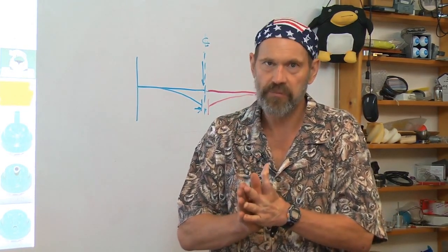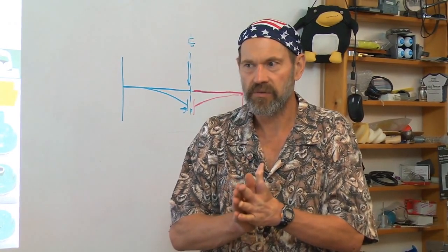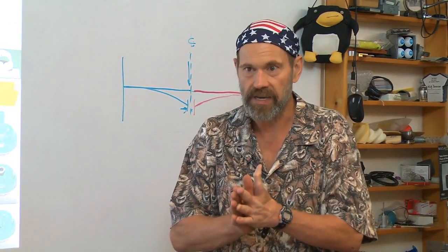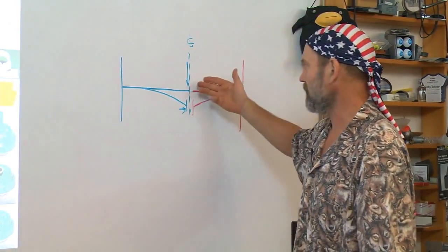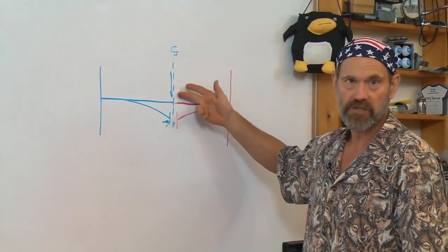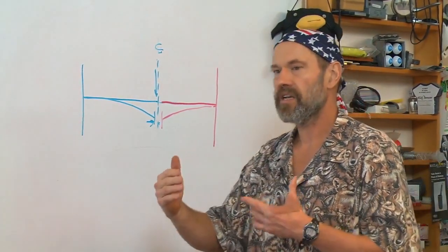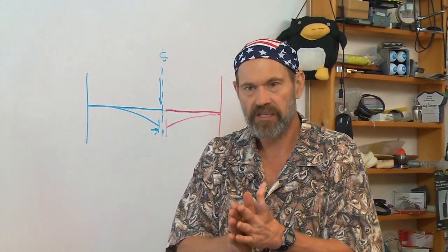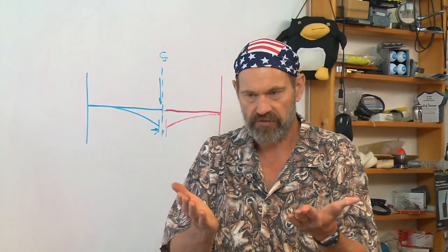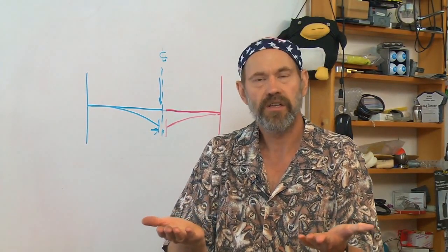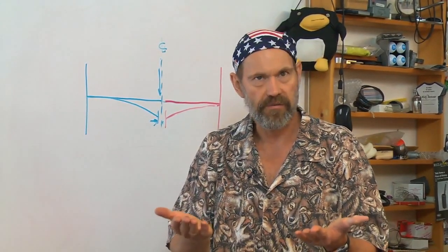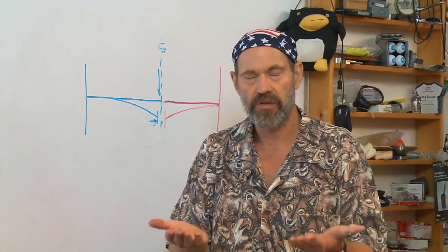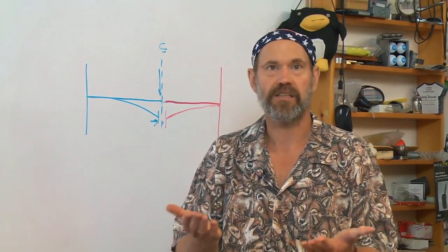If they are a problem for your machine, you ask yourself the question, well, how can I make them go away by either just making it much stronger, stiffer, but that doesn't always get rid of the parasitic motion. For example, here, it's just a function of the geometry. Or how can I use reciprocity or make a structure a mirror image of itself and use one parasitic motion to cancel another? That's a very, very powerful part of design, is that use of reciprocity and canceling error motions.